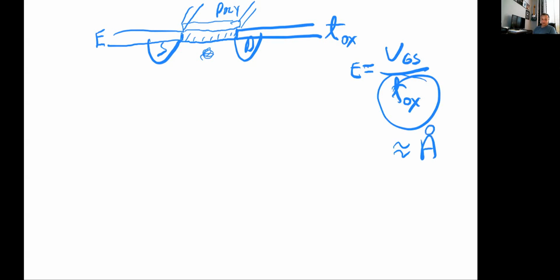That's how we measure that. They're really thin layers of oxide. So if this oxide is thin, what that means is that for regular voltages, whatever it is, it doesn't matter, this is a huge electric field, in the millions of volts per meter. So that can put a stress on that oxide.